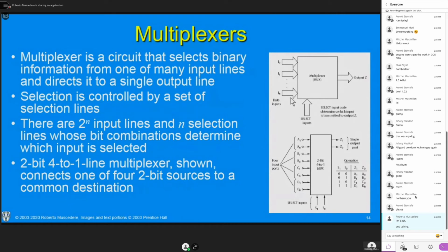So in this particular case, we can see this is just a standard multiplexer. The idea is you have some select bits here that pass I to some output Z. So it's either I0, I1, or up to IN, it looks like over here. Now, multiplexers can be applied in many different ways. Usually we say something like a 4-to-1 mux. So here we have 4 sets of data, and one of these sets of data is going to go to Z. But you'll notice Z is 2 bits. So this is a 2-bit 4-to-1 multiplexer where our inputs are 2 bits, and one of these sets of 2 bits goes to Z depending on the selection pins S.